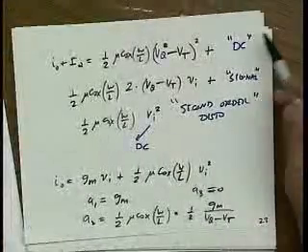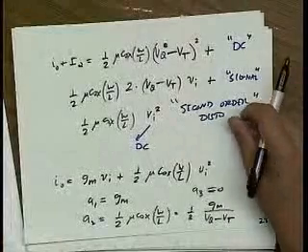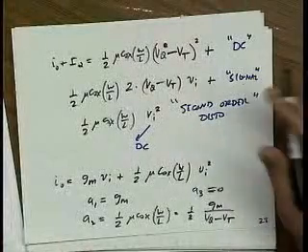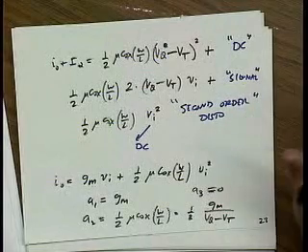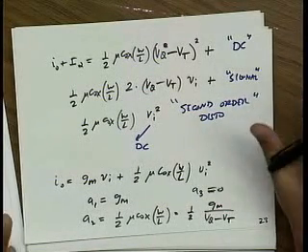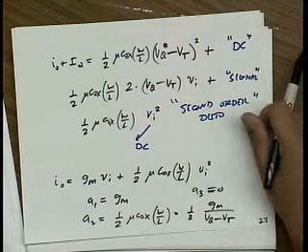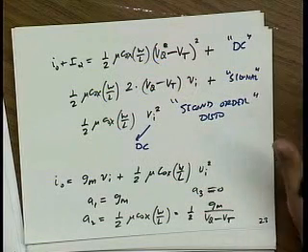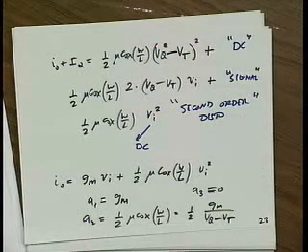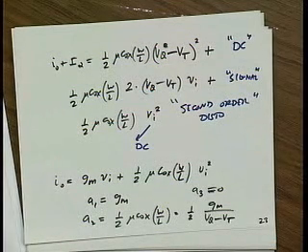Remember, we're using this equation from the square law device. Basically, this is fantasy. If you had a channel length of 20 micron, great, you can use this equation. Even there, it doesn't take into account the body effect. So really, that equation is fantasy. In reality, it's much more complicated. We have to take into consideration diffusion current in a MOSFET.